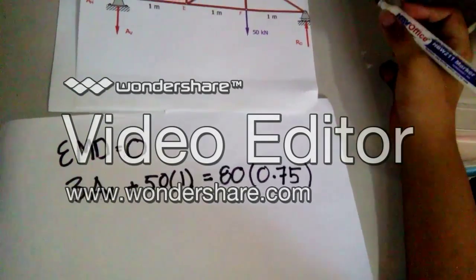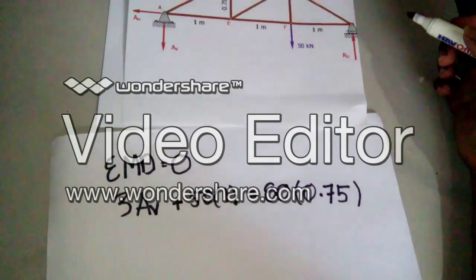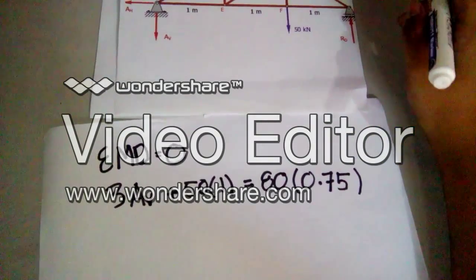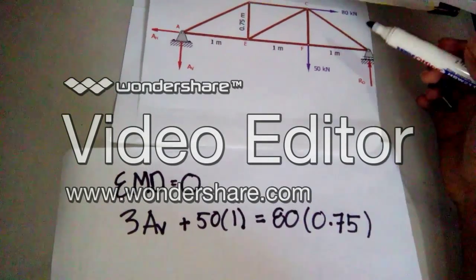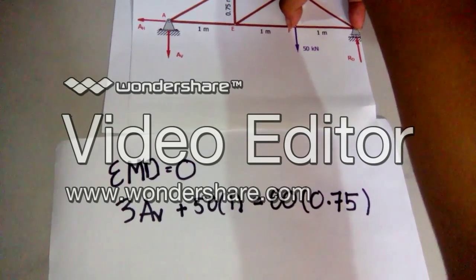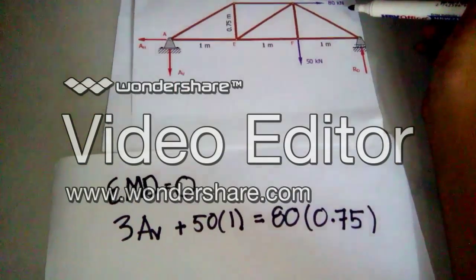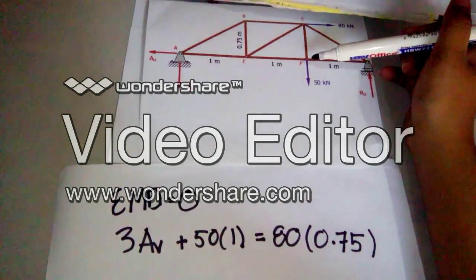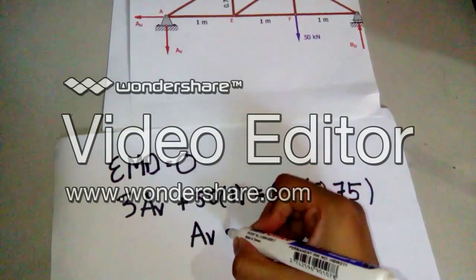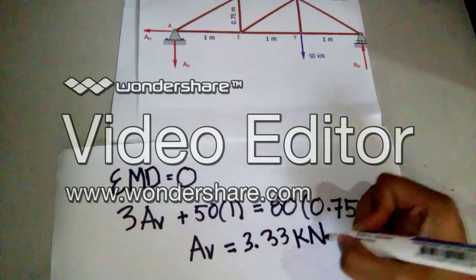This is the equation for getting the AV using the summation of moment in joint D. We have 3AV plus 50 times 1, which is the distance from joint D to joint F, and 80 times 0.75, which is the vertical distance of joint C to joint D. And we have AV equal to 3.33 kilonewton.